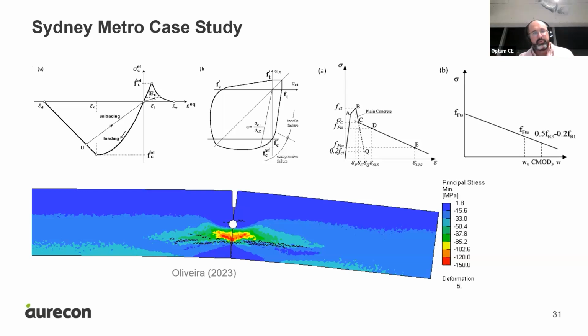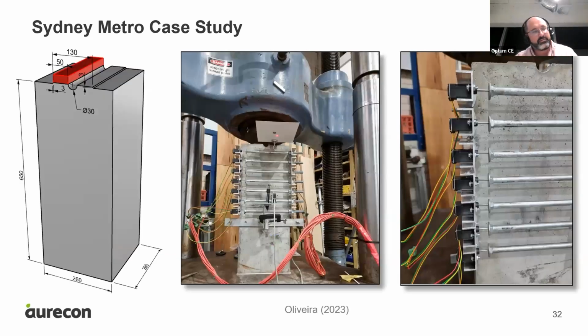So what we did here, we simulated the rotation of the segments, and we got to a point that we said, hang on, we don't think that the resistance is as low as we thought, like 5 times under. Our fiber reinforced concrete segment without conventional reinforcement is able to resist this. And we go through the same exercise. We are saying that the resistance is 5 times greater.